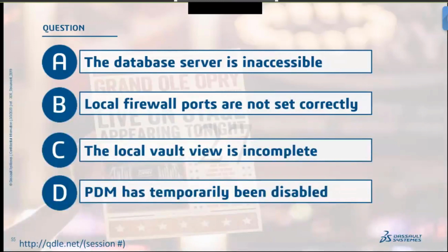All right. So again, we have options like either the database server is inaccessible, the local firewall ports are not set correctly and we could have some ports being blocked there, the local vault view is incomplete, either through the installation or something else being modified, or PDM has temporarily been disabled.